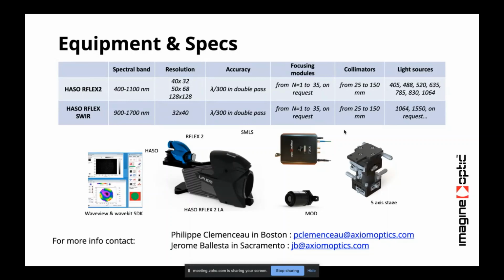For example, you can enlarge the beam and then focus it to the F number needed to characterize the concave mirror in autocollimation, by focusing the light at the center of curvature of the concave mirror. We don't have standard modules dedicated to this application, but if you want, we can try to design a specific one to create a converging beam, in order to set the concave mirror at the center of curvature and retrieve the autocollimation thanks to this mirror.